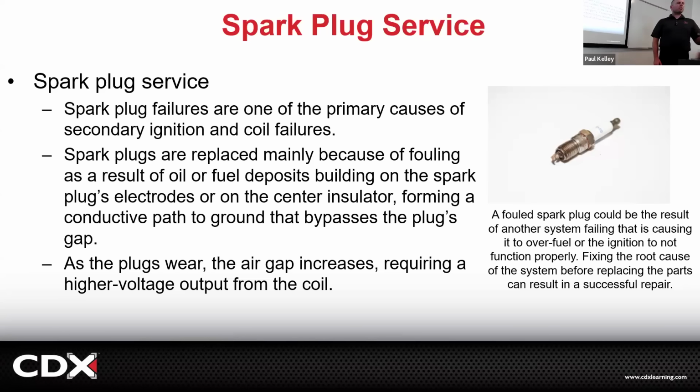All right, so we don't really do that, but it was a cool thing that you should know. So you know what we're probably going to do? We're going to replace them. If the spark plugs are fouled, you pull them out, you look at them. It's on the next slide. They're fouled, you replace them. But that's not it, though.